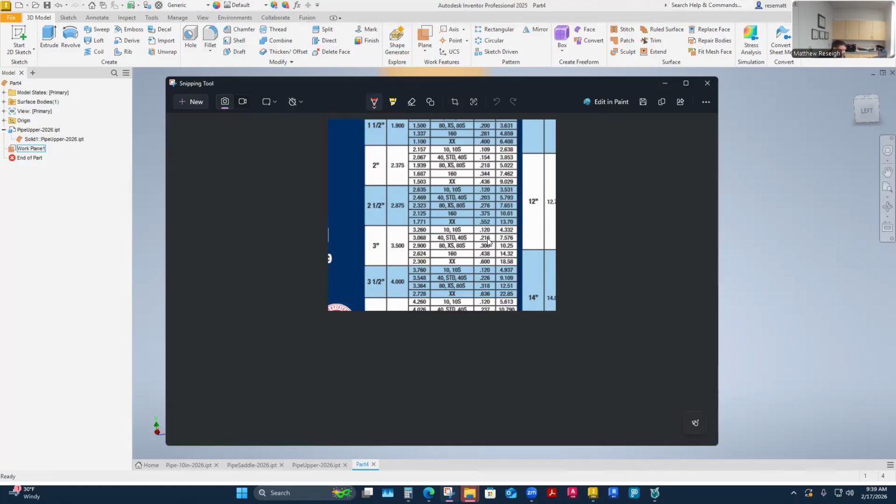I think the way the engineer delivered this to us is we're trying to source stuff that's just on the shelf. If you think of a pipe support, it's not a highly accurate piece of a part, but it does need to function well. And I'm trying to source something that will work together without a bunch of machining work that would increase the cost of this part. If I can just buy a couple pieces of pipe, chop them, cope them, they fit together, they're weldable, even though the gaps might be a little bit bigger, for this application, it could be just what we need. It would be faster and cheaper than machining a part for a pipe support. Although some pipe supports get pretty critical and they do get machined, and there are some reasons, I'm trying to go simple here, the KISS method.